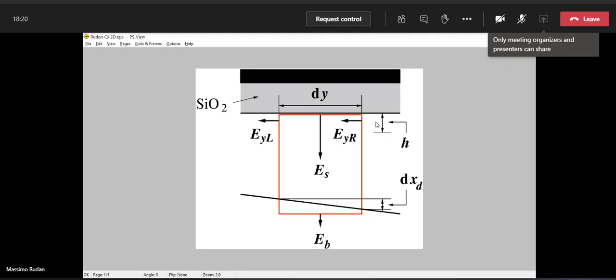And in particular, to calculate the charge per unit area present in the semiconductor, we were using cylinder number 3, in which the left face, in this case it is the upper face because this figure is rotated, is very close to the interface. So it is still inside silicon, so we can use the permittivity of silicon, but it is inside, very near to the surface.